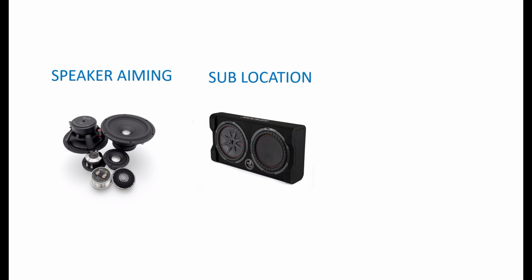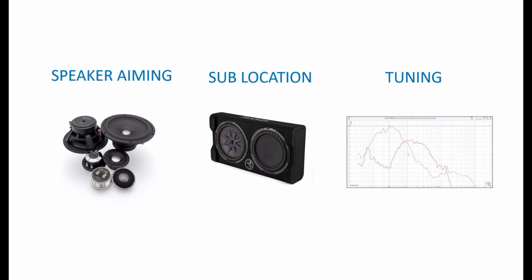Well, that's great, Socket, but what does it have to do with car audio design? Well, you can't do much about your seating position or the windscreen or stuff like that. Yes, you can move your seat back and forward, but it needs to be in a position where you can operate the car and reach the pedals and things like that. So you're kind of stuck with the geometry of the physical car itself. But what you can do is you can change the speaker aiming, you can change the position of your subwoofer, and if you've got a DSP, you can change things like the timing and the delays and the levels and the EQ to shape the speaker responses that you want.